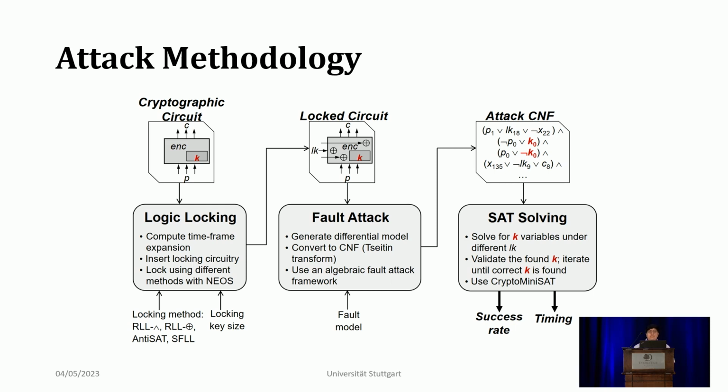This time frame expanded circuit is then locked using NEOS, which is an open source netlist encryption and obfuscation suite, based on the different locking parameters that you can choose. Once we have this locked cryptographic circuit, an attack formula is constructed using our algebraic fault attack framework called AutoFault.